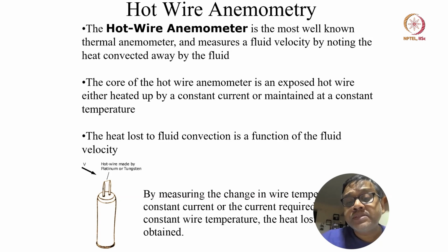Now here comes the crunch, that it is actually measuring the fluid velocity by noting the heat that is convected away. So it is not directly measuring the flow velocity. It uses heat transfer to find out what is going to be the flow velocity.